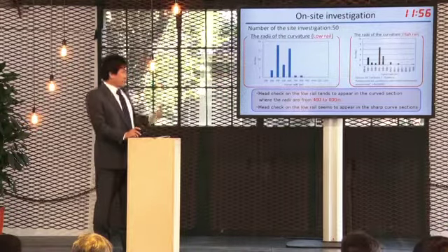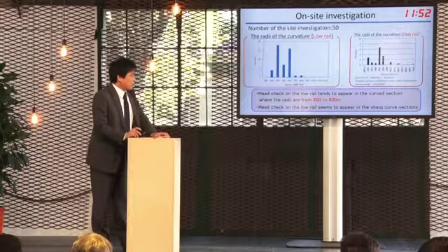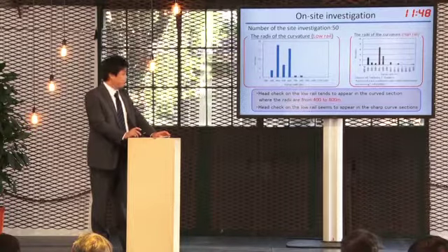According to the left figures, head check of the low rail tend to appear in the curved section where the radii are from 400 to 600 meters. From the comparison between left and right figures, head check of the low rail seems to appear in the sharp curved sections.